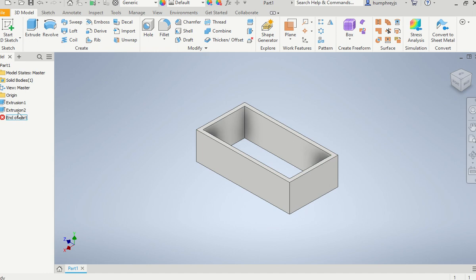So another thing to point out, guys, here is if you had loads of sketches down here which aren't turned into extrusions, because every sketch turns into an extrusion, the computer program can get quite confused. So make sure when you draw a sketch, you turn it into an extrusion. And if you don't do that, then let's just delete the sketch. Another thing you might find is you don't know what's going on. I'll show you that with my next bit actually.